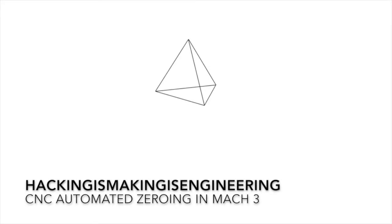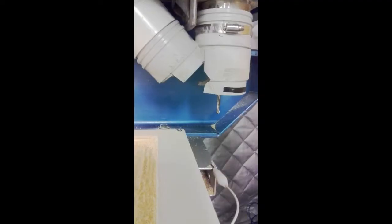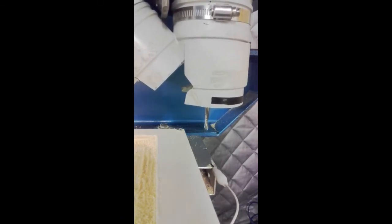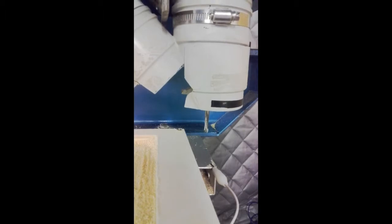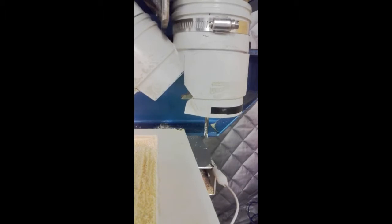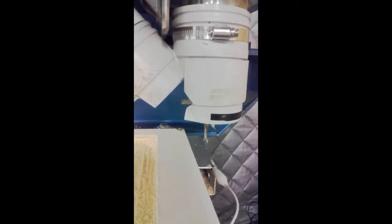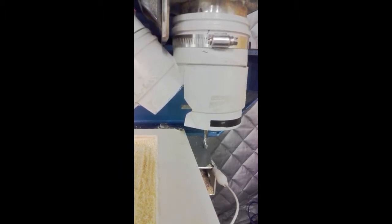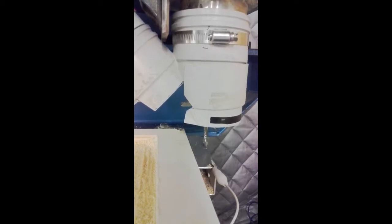In this video, I'm going to be explaining how I made a zeroing script for my CNC machine. Here is the machine zeroing itself. It moves from the home position and then it plunges downwards. Now there's a cable connected to the aluminium block in the bottom left-hand corner of the picture. And when the tool touches it, it completes a circuit telling it that it's reached the bottom and that's the zero position of the tool.